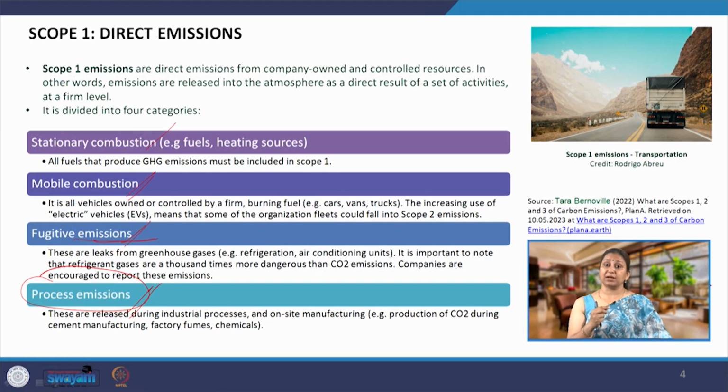And how do we know that? How would companies know that the gas has leaked? Because there is a certain pressure that has to be maintained and we know the total volume. So, in the maintenance process, to continue to run the plant at a certain efficiency, these pressures and the volume of the gas that is inside the system in a closed loop are constantly monitored and we need to refill the gas.